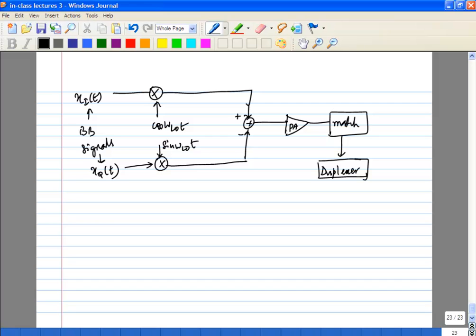In a typical FDD system, it will go into a duplexer. You go to the antenna, and of course, the other side of the duplexer goes to the RX. Okay. So this is the simplest TX transmitter. It can be used, but there is one big problem. If you look at this, you might need a band pass filter here in some cases, okay.